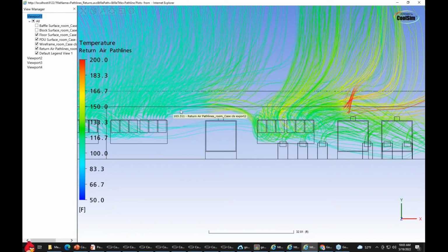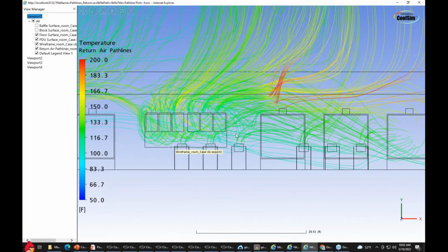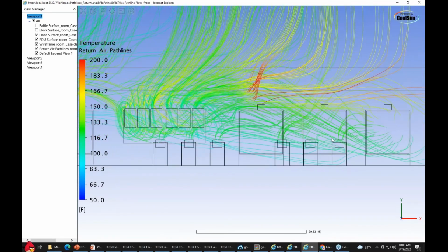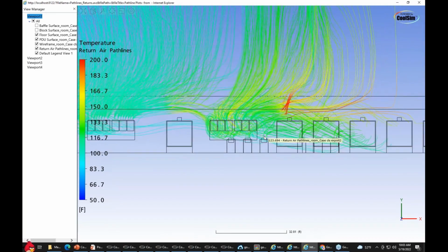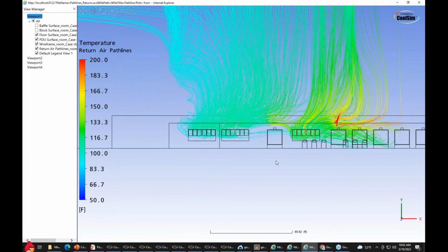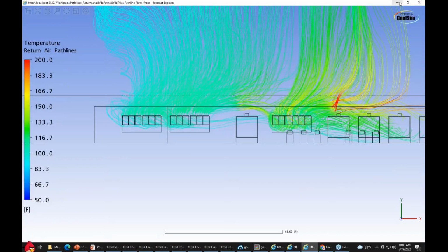So the air is coming out of this one. The wind's blowing from the left to the right. It's being sucked into the intakes of this one. This one is contaminating the others. We've got a downstream effect going on here. It's not good. So this helps you to perform what-if studies on exterior flows, and it's quite effective and will give you a lot of help in these kinds of cases.